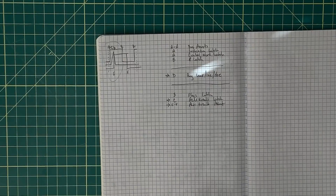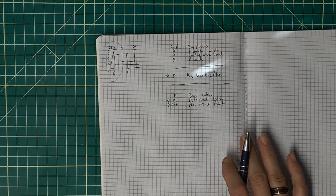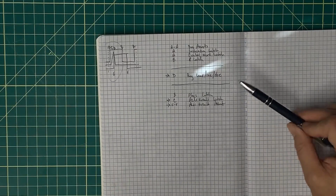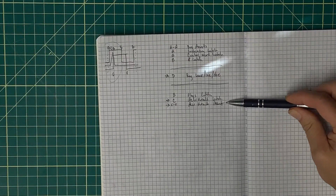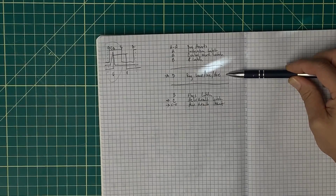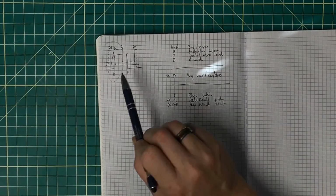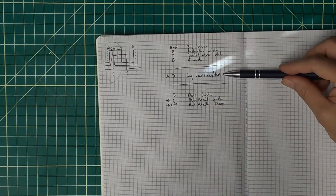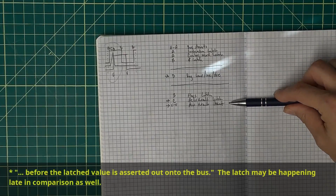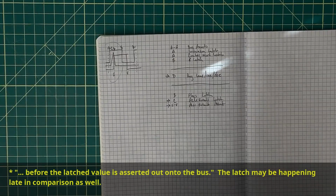And I need to make sure that all three of those signals are actually happening in the correct sequence, so that at the end of all of that, I end up having a result that gets added and then latched and then asserted out onto the main bus and then loaded off the main bus in the correct sequence. My prediction is that the load, increment, and decrement at the register is happening before I'm actually asserting the result out onto the bus. And that's what I need to start measuring. Now I've got C in there as well.